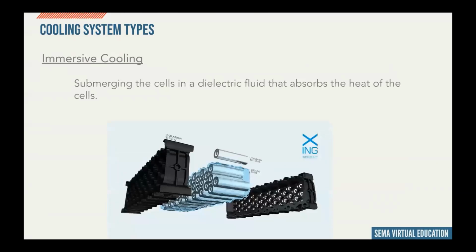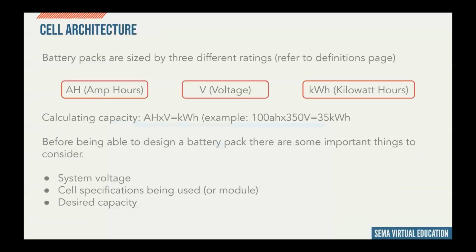Immersive or submersive cooling is a design where the cells are actually submerged in a dielectric fluid absorbing the heat of the cells. This has become very, very popular, and there are companies that provide this as a solution in modules or complete packs, because this is a way to get a cooling fluid to have 100% contact to the cell. And they're typically a higher weight, higher cost, and higher complexity, but they are very, very effective cooling systems.